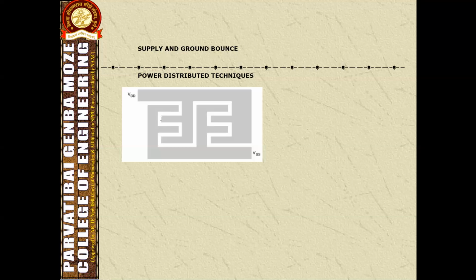If the logic gates use few standard transistor sizes, computing the power in a line is challenging. So, in order to design a large integrated circuit, simple rules are chosen for the power supply width. Hence, metal migration is the problem in a power supply distribution.